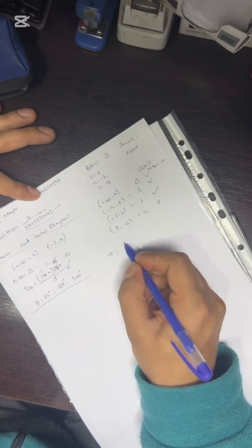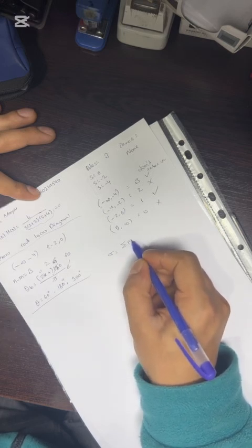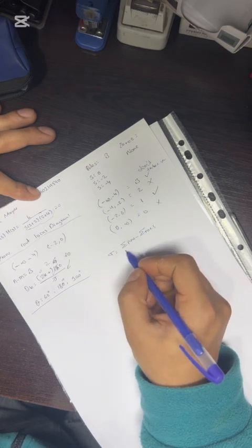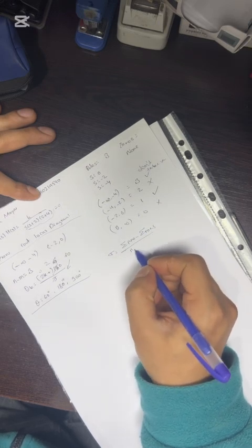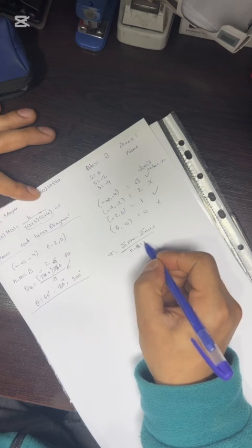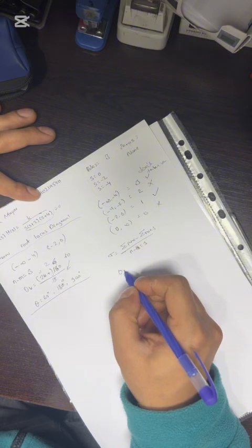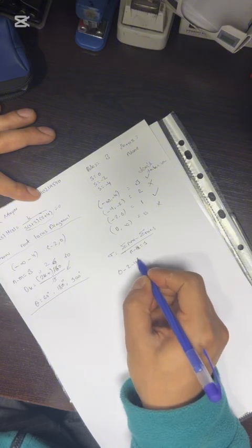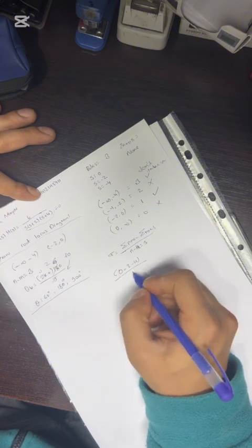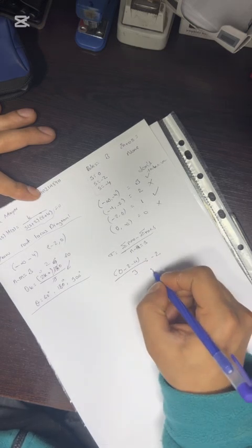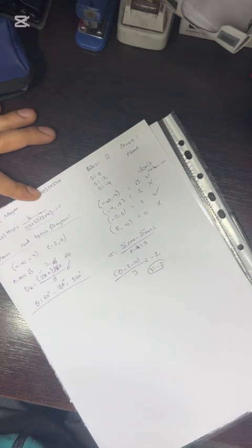It is equal to the sum of the poles minus the sum of the zeros, divided by n minus m, which is equal to 3. As we don't have zeros, the sum of 0, minus 2, minus 4, these are our poles, divided by 3, which is equal to minus 2. So s is equal to minus 2, as we can see here. So we have a breaking point.